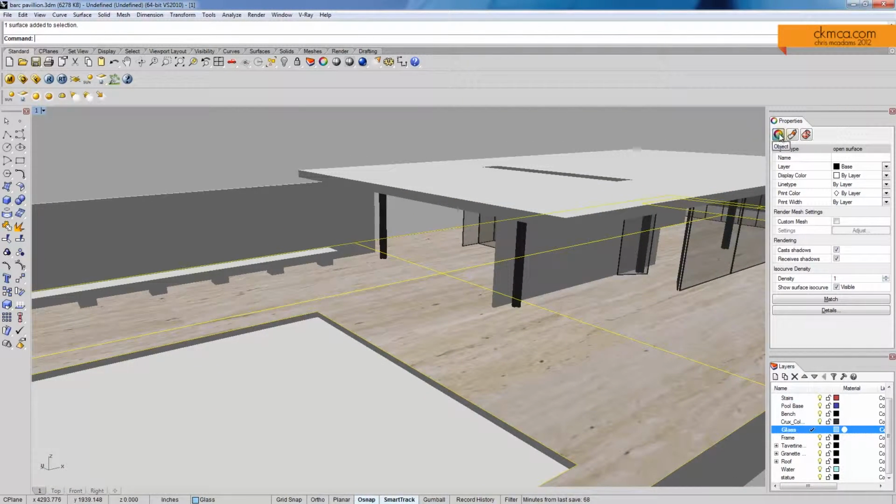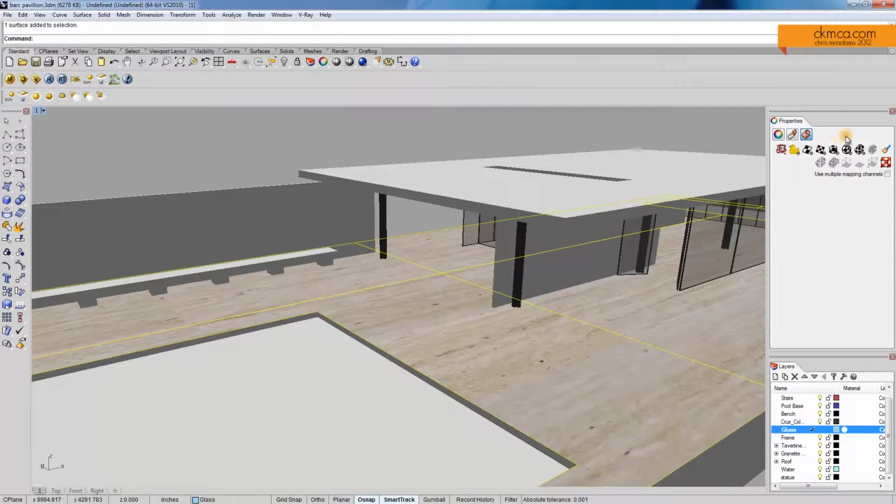And just like before when we edited the light, we do have options under properties that we can drill down into. So here I'm going to come to texture mapping. In Rhino 4, it's again the drop-down menu. And I'm going to apply several different things here. We'll cover them little by little, but for this one, we just want a planar map.